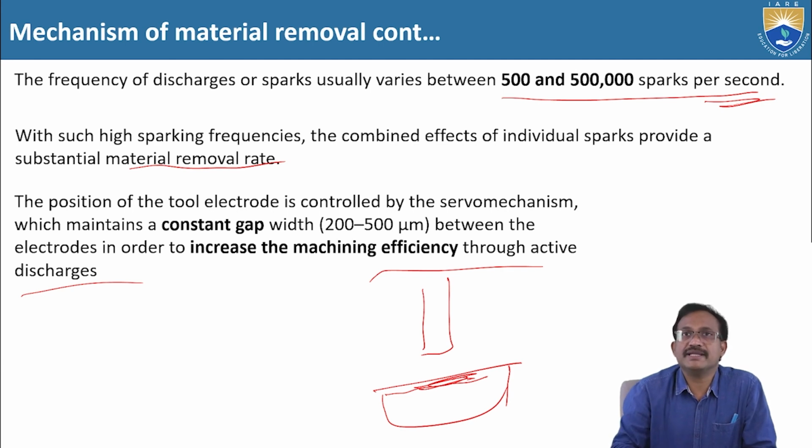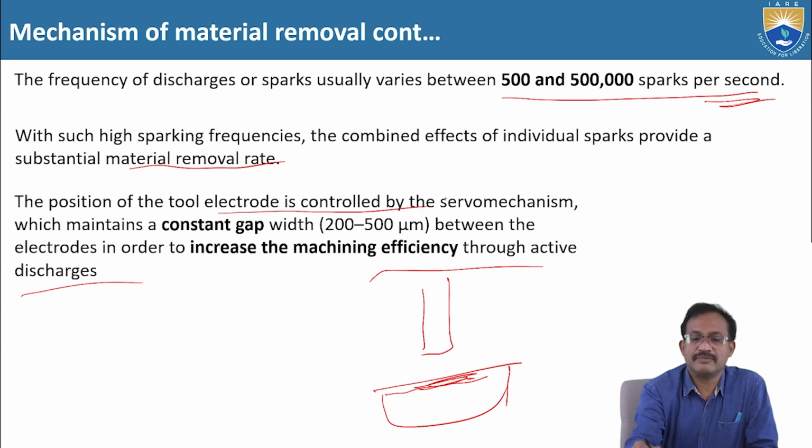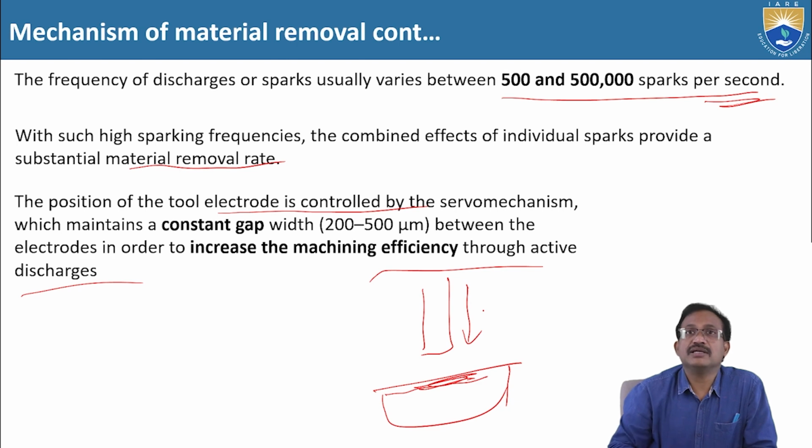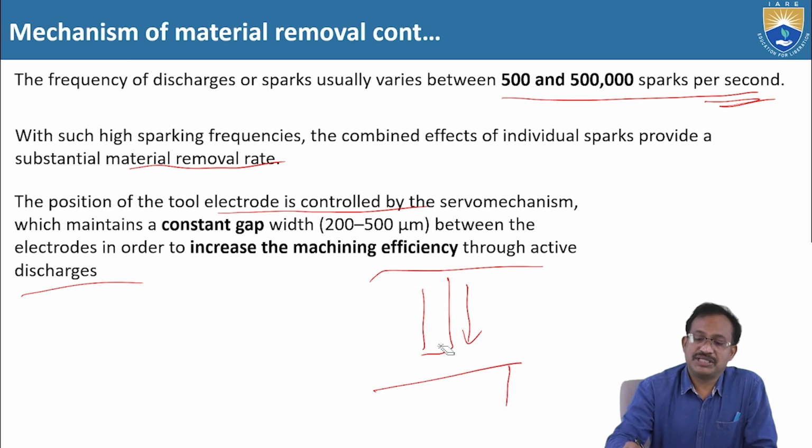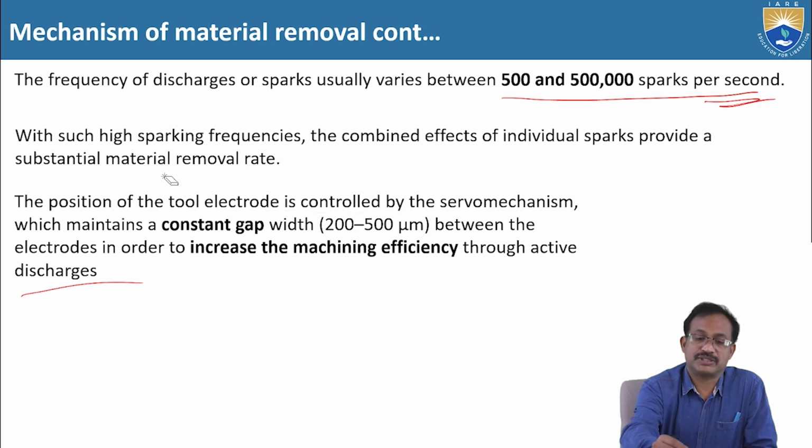In order to maintain the same gap, a servo control mechanism is adopted to feed the tool towards the workpiece. However, the workpiece will be moved in X, Y and Z directions for the machining of contour shapes.